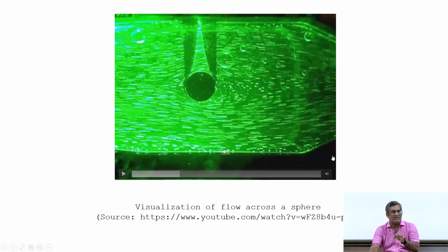On the wall it is zero, and in the vicinity of the wall it will be some small value. This is the reason why you are able to see the particles. So the point is, this has to be ensured in the PIV image: that you actually capture a frozen flow field. Frozen flow field means the particles are almost not moving. Only then you will get the correct image of the particles.